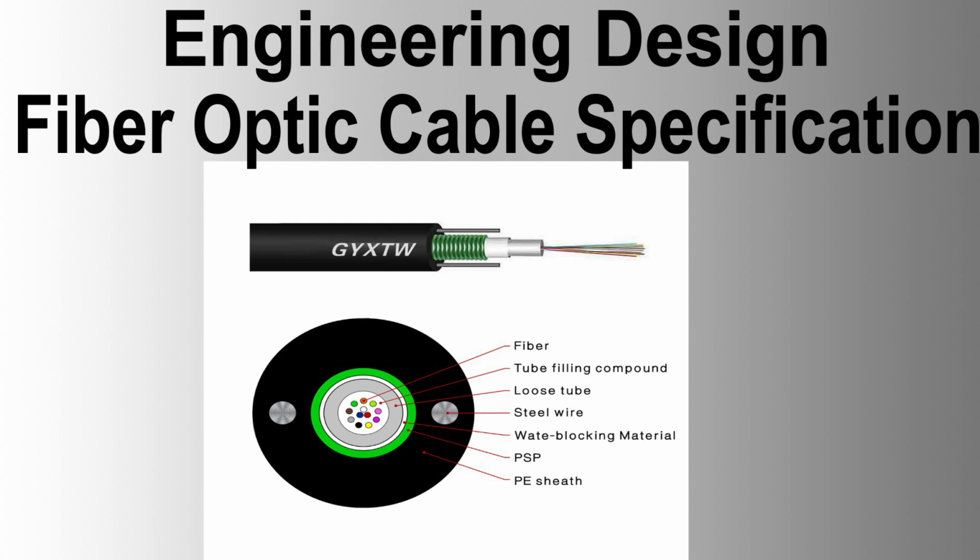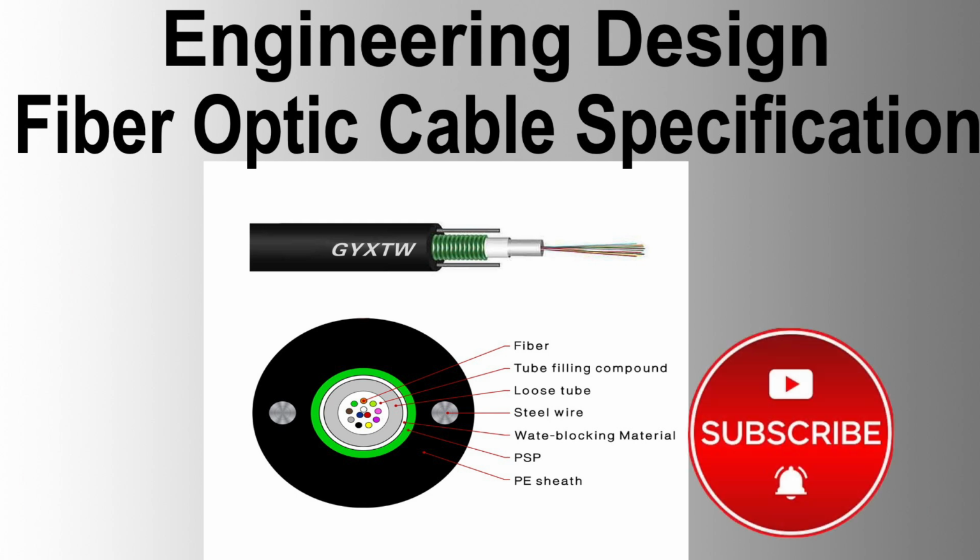structure. Filler rods. Optionally used in lower fiber count cables to keep the structure round. Aramid yarn layer, engineered to provide the required level of tensile strength. Superabsorbent polymer tape, wrapped around the aramid yarn. Ripcords, 1 or 2 ripcords are included. Sheaths, lead inner sheath and HDPE outer sheath, subject to vendor design.